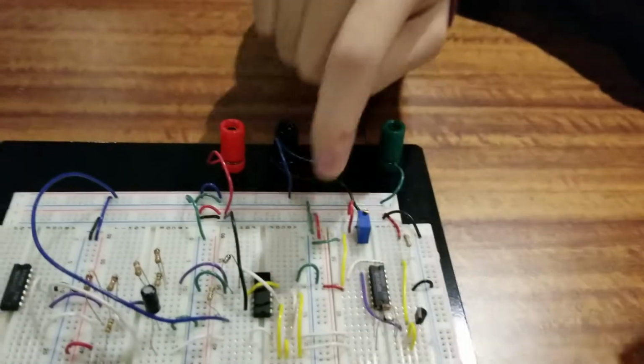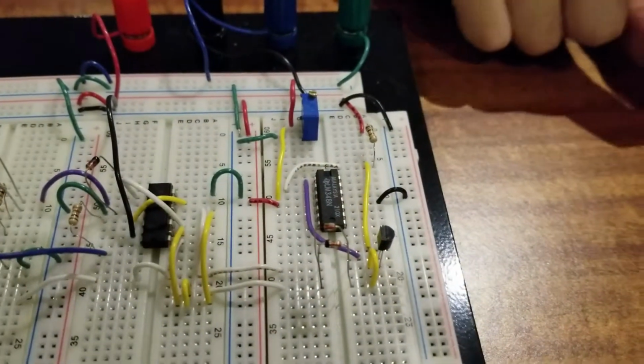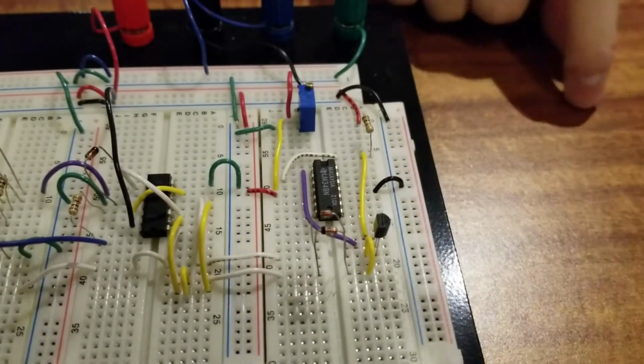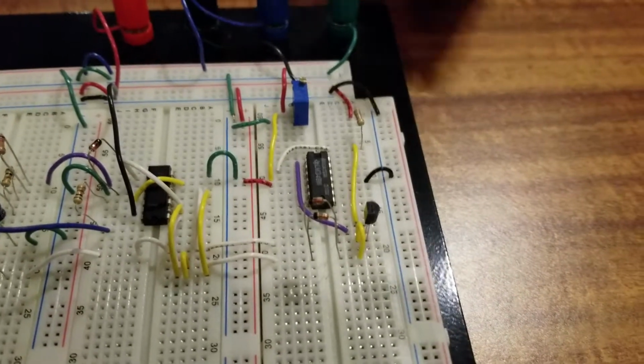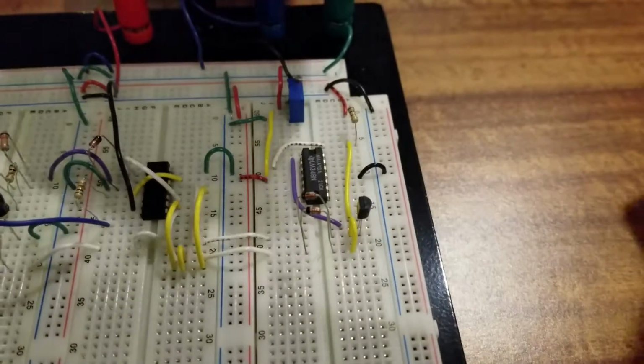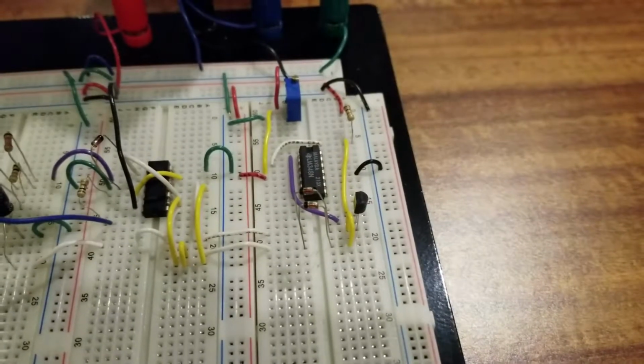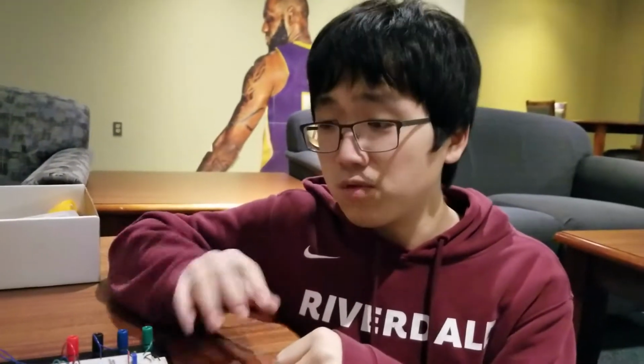All right, I'm here to talk about Lab 8. This first part, this part of the circuit over here, is our part A, a voltage-driven current source. Basically, we feed 15 volts into the circuit, and this potentiometer is there to manipulate how many volts are being driven into this subcircuit. The purpose of this subcircuit is to convert a constant DC input into a constant current source that flows through the rest of the circuit.